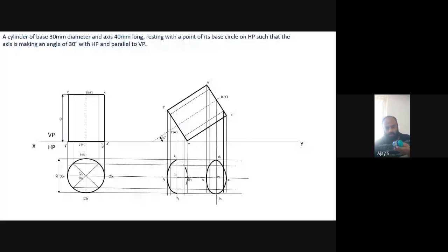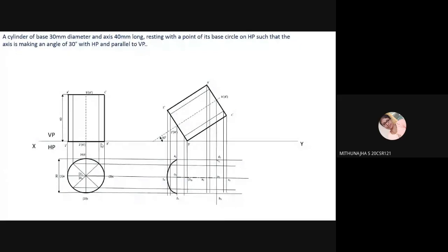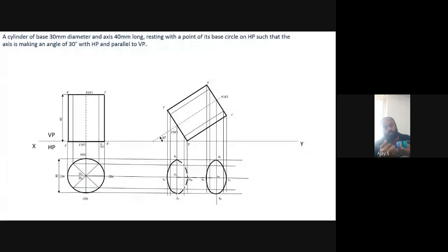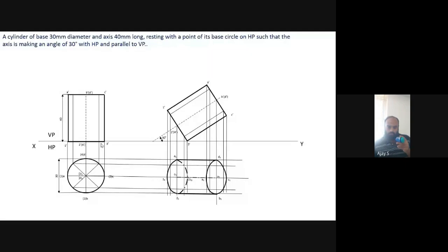Is it right? We can see the front part, top base over here as a proper circle, and the bottom base half you are able to see. Yes or no? Yes, sir. Correct? Then what I do is I draw this hidden part. Next, I join these two generators, whichever you see, this top generator and bottom generator. I'll just draw. So does this look like the image seen? Yes, sir. Okay.